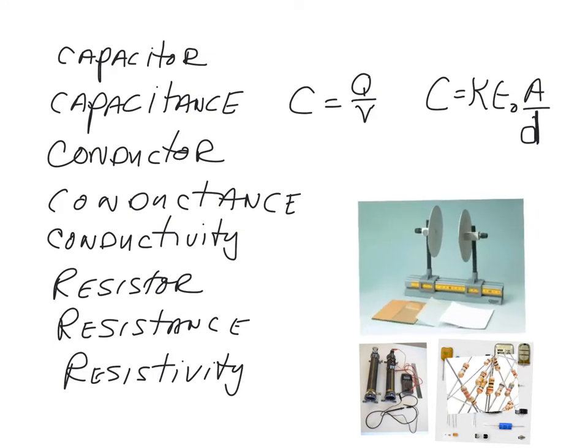What the capacitor depends on is the characteristics of the device. So it depends on the area of the plates, the separation of the plates inversely, and the epsilon naught, the electrostatic constant, and the material between the plates. So if we have air, this is 1, but if we put some other material, that will raise it. So 3 factors: the material between the plates, the distance between the plates, and the area of the plates. So this is what we learned last week.